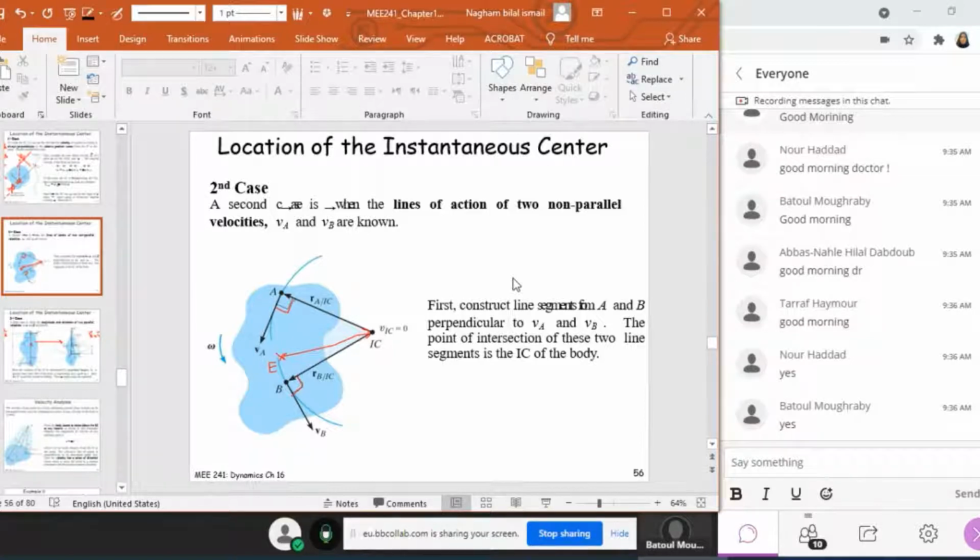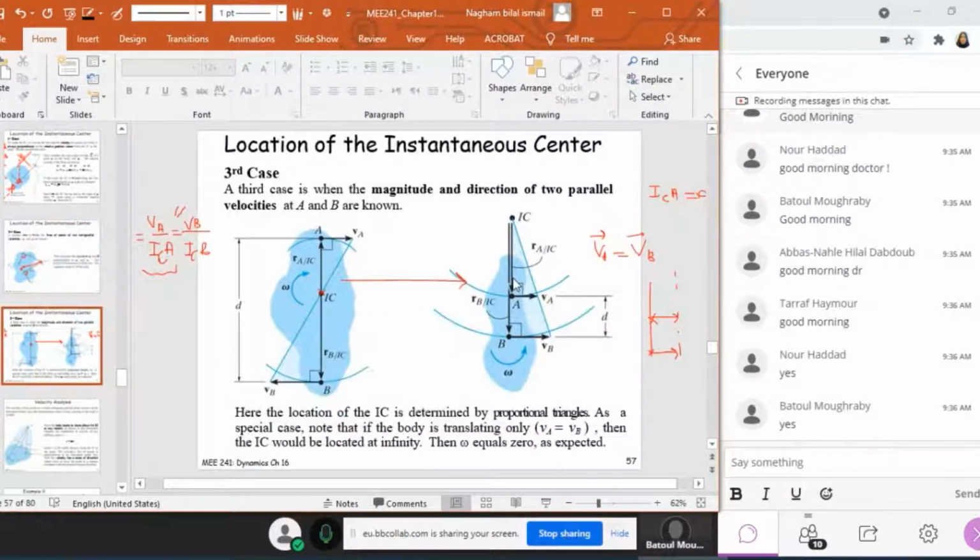So remember, guys, from the general plane motion, if V is equal to 0, this doesn't mean that A is equal to 0. V could be equal to 0 at this instant, but I can have an acceleration. So don't be confused with this fact. Now, if I have two parallel velocities, however, with their starting points A and B lying on the same perpendicular line to VA and VB, the instantaneous center of zero velocity will be the intersection of two lines. The first line is the line joining their ends, and the second line is the line joining their starting points, right?